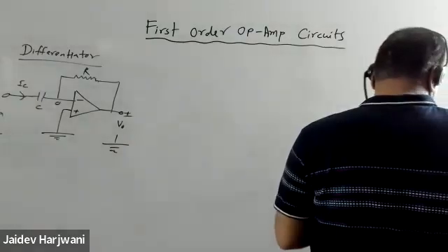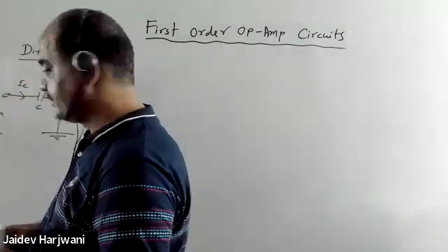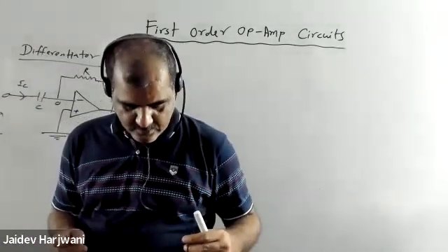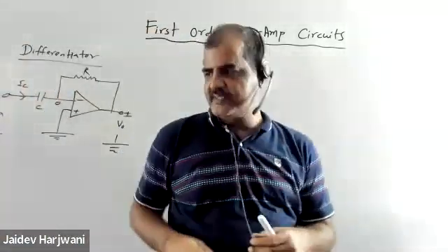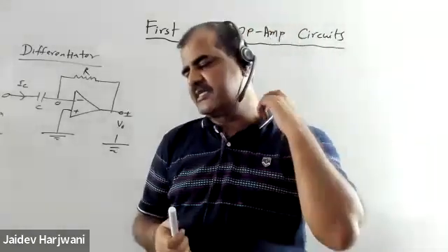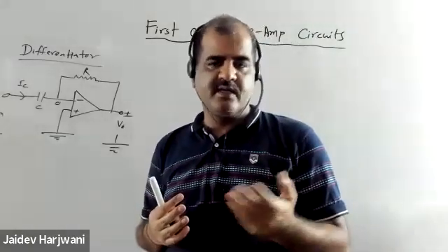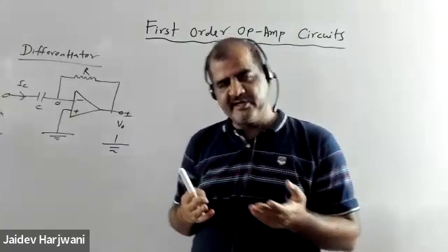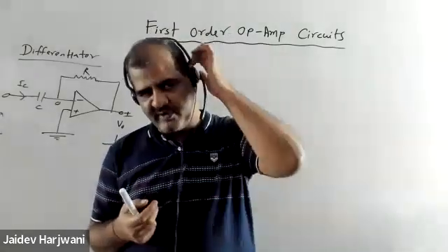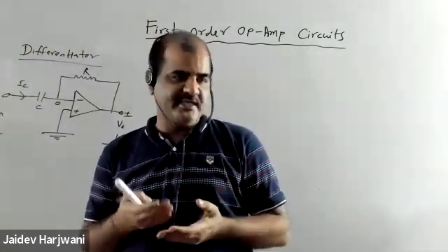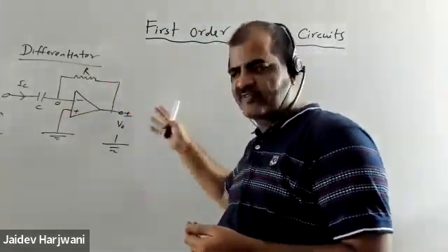सर वैसे फर्स्ट ऑर्डर का तो यहाँ पे मतलब क्या होगा? तो ये जैसे दोनों सर्किट्स फर्स्ट ऑर्डर ओप-एम्प सर्किट्स हैं, तो हाँ. फिर फर्स्ट ऑर्डर का क्या मतलब है? फर्स्ट ऑर्डर में डिफरेंशियल इक्वेशन है ना, जैसे हमने नेटवर्क एनालिसिस किया था, जब सर्किट में रेजिस्टर एलिमेंट था, देन किरचॉफ लॉ लगाने से जो इक्वेशंस आ रही थी वो सब अलजेब्रिक इक्वेशंस थी. ओके, वी और आई में. और व्हेन वी इंट्रोड्यूस दिस आरसी और आरएल टुगेदर इन सर्किट, तो किरचॉफ लॉ लगाने से जो इक्वेशंस आ रही थी वो डिफरेंशियल फॉर्म में आ रही थी. अभी भी इक्वेशन डिफरेंशियल फॉर्म में आ रही है ना.